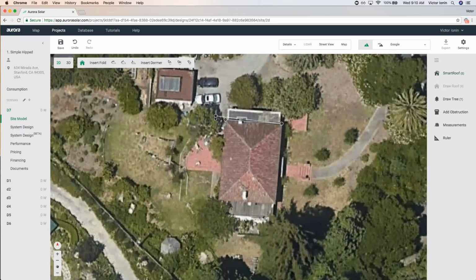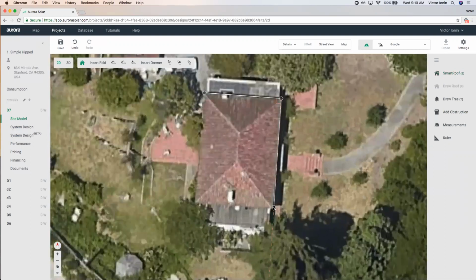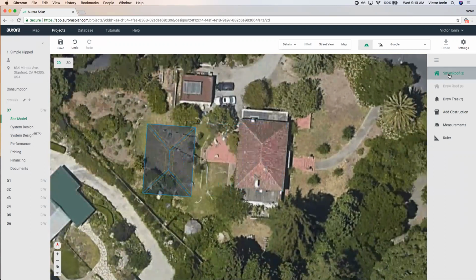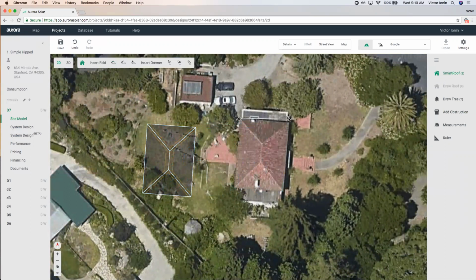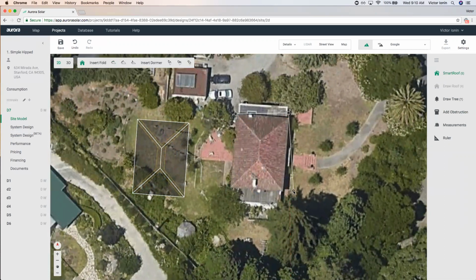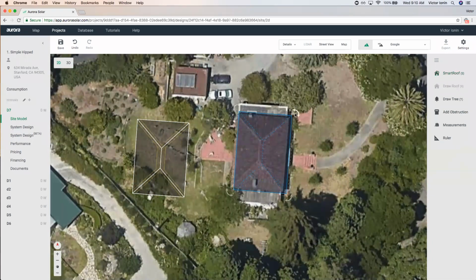Now, after you draw your first line, you'll see that all follow-up lines will try to snap to 90 degrees of the previous line. I highly recommend that you allow the snapping to occur, and that would ensure that you drew an accurate drawing. Now, let's say you messed up and you misclicked the first line. You can see that my snaps are really going to be off. You have two options. You can, of course, just finish your drawing following the 90-degree snap and then rotate your image. And I'll show you how to do that in just a second.